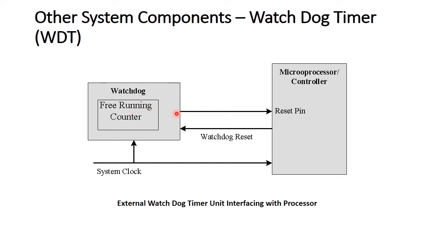The output of the watchdog timer is connected to the reset pin because it causes resetting of the microprocessor or controller. And the request for the watchdog operation is sent by the microprocessor or controller whenever there is a runtime error in the firmware execution.